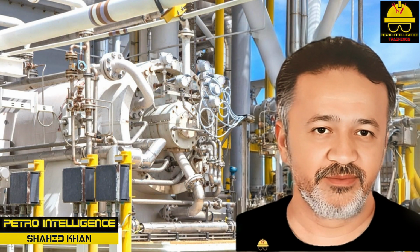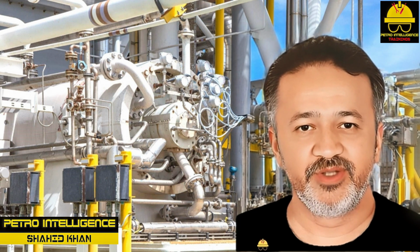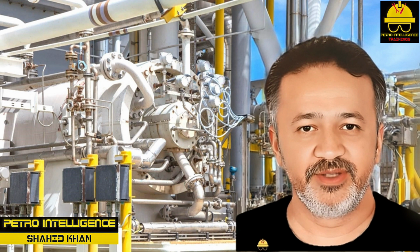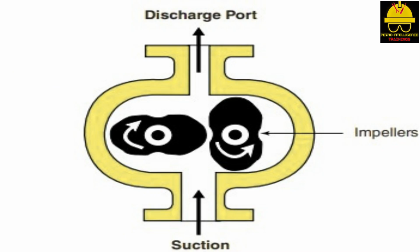Lobe compressors. Lobe compressors are characterized by the two kidney bean-shaped impellers used to trap and transfer gases as shown in picture. The close clearances between the casing and impellers are maintained by a set of timing gears. During operation, the two impellers move in opposite directions on parallel-mounted shafts as the lobes sweep across the suction port.